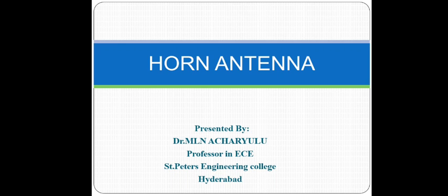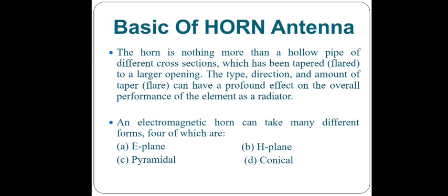What are the drawbacks? The VSWR increases in aperture antennas and it gives poor radiation. This type of antenna is applicable only in surface search radar applications. But the horn antenna has a lot of applications in the communication area. So we are going to talk about the basics of the horn. A horn is a flared out waveguide generally, right? So here, this is the horn antenna.